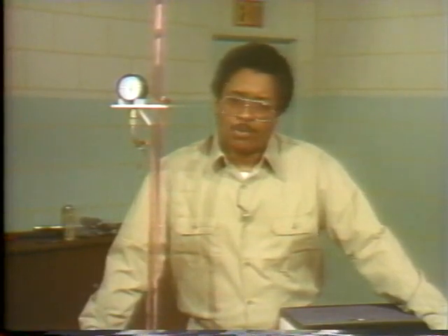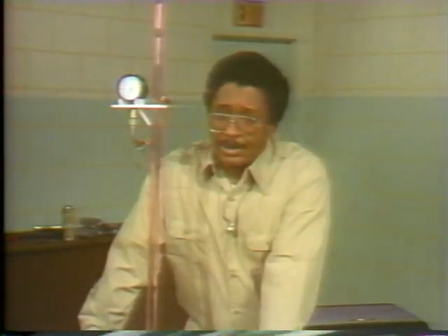Okay, what have we learned so far? We've learned that pressure is the amount of force that is exerted on a given surface. And we've also learned that the formula P equals F divided by A can be used to determine pressure. We've also learned that the pressure exerted by a fluid does not depend on the volume of the fluid, but rather on the height of the fluid above the point where the pressure is being measured. Finally, we've learned that a column of water with a static head of 1 foot of water exerts a pressure of 0.43 psi.